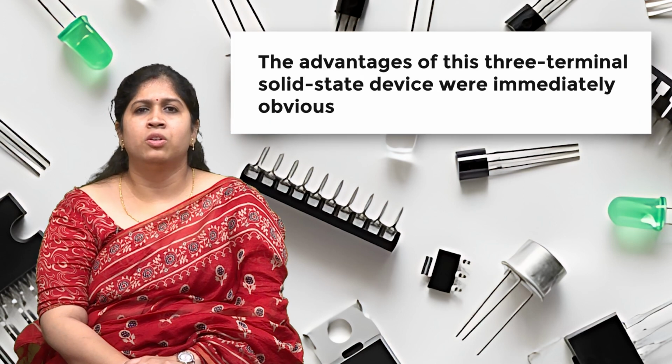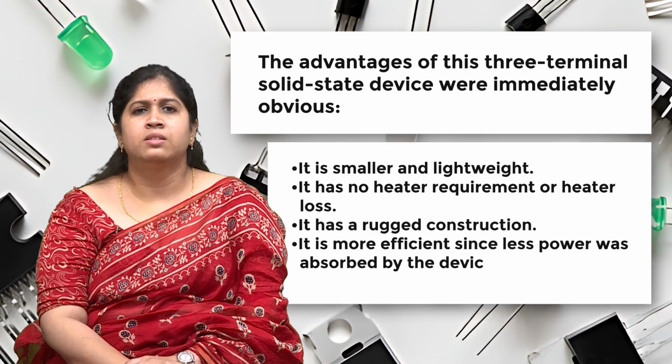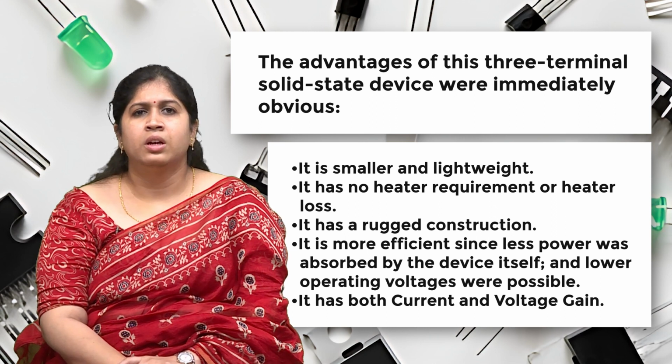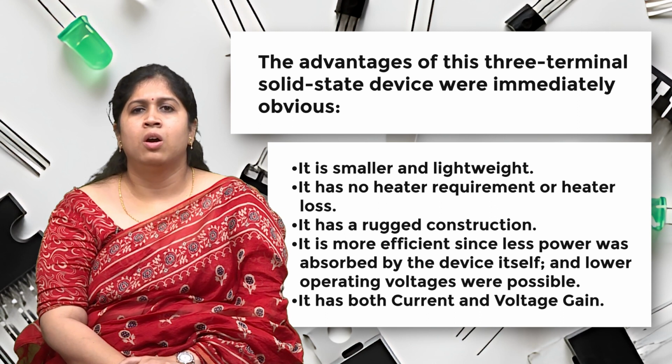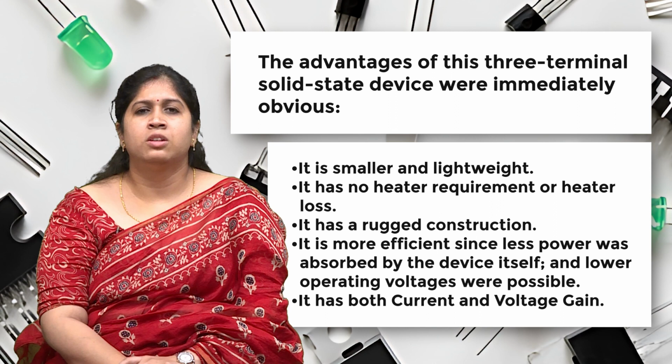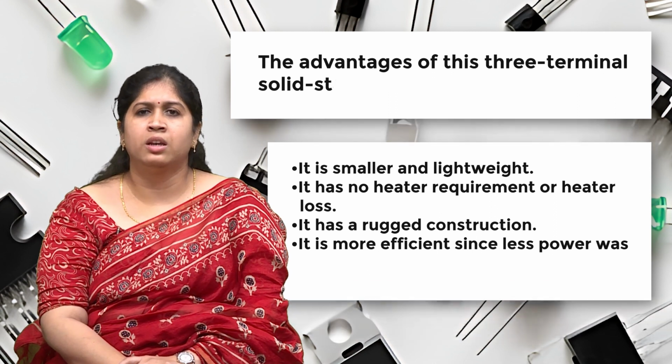The advantages of a three-terminal solid state device were immediately obvious. It is smaller and lightweight. It has no heater requirement or heater loss. It has a rugged construction. It is more efficient since less power is absorbed by the device itself and lower operating voltage is possible. It has both current and voltage gain.